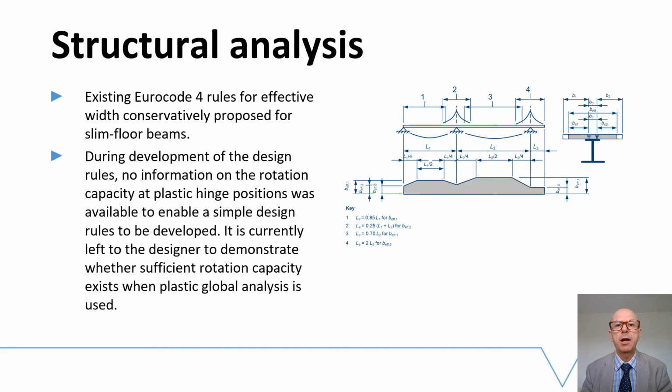However, during the project team's work, it was found that there was insufficient data to enable general design rules to be developed, and as a consequence of this, a conservative approach is proposed by using the existing effective width rules in Eurocode 4.